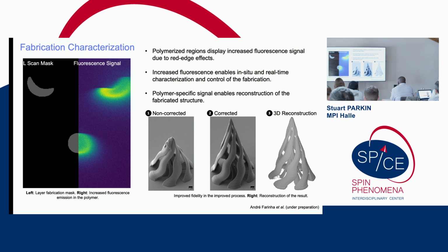And I also wanted to point out that Andre went beyond any existing microscope, as far as we know, by incorporating a fluorescent signal. So we have several different lasers. I'm not going to discuss, you need 2 lasers for the STED and another laser to detect the fluorescence, to fluoresce this molecule. And so basically he makes on-the-fly corrections because the polymer, it's a liquid, it's polymerizing, and this is without any corrections. But after he corrects using this luminescence to basically tell the computer system to move the laser beam slightly differently, then he can build structures that are more perfect. So we believe this is, again, a major advance in this technology.